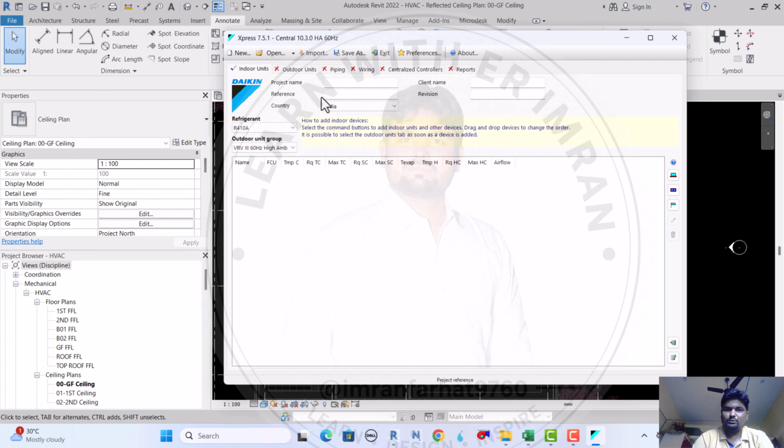This is the new page. Project name. Save as is showing here. Also here save and exit, there is nothing too complicated. Here the unit, diagram, data input, advanced. You can limit the maximum connection ratio. The connection ratio is indoor unit divided by outdoor unit. You can limit it up to 100%, otherwise no need.